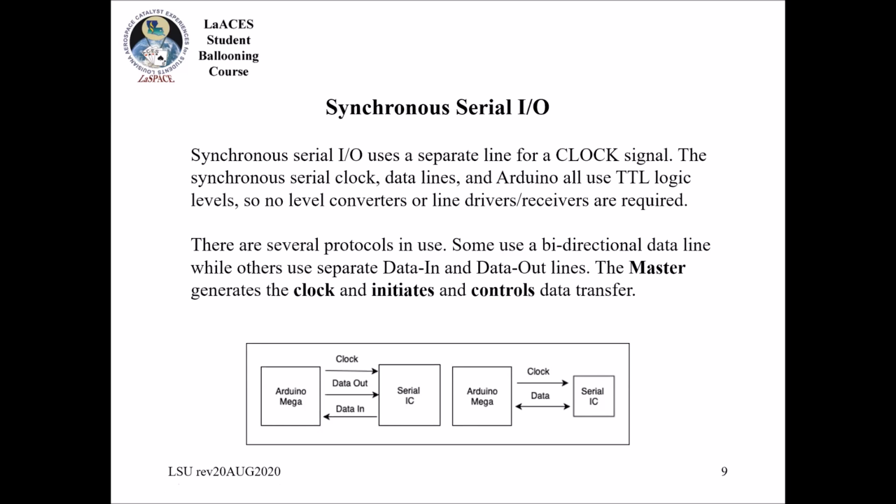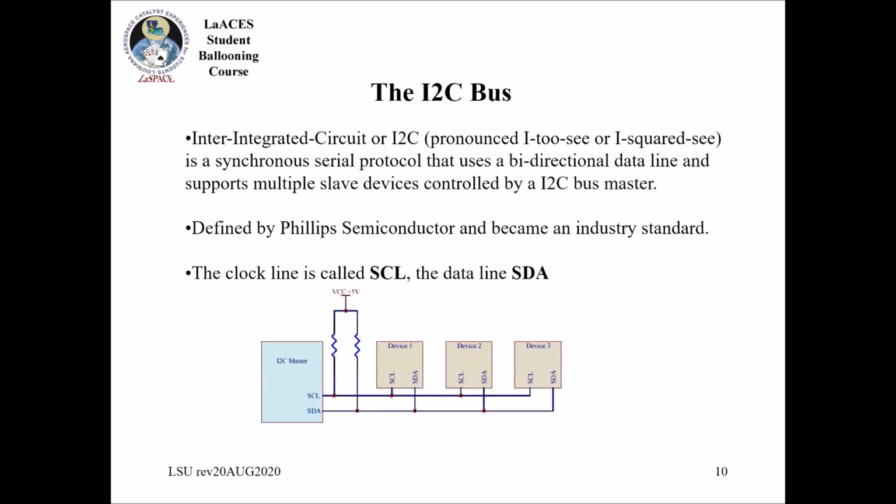So that's really important. Fortunately, with I2C, that's one nice thing, you just connect them all to the same pins, and you also don't require separate pins. These things also don't require a chip select, like what the SPI would use. With the SPI, you have to have a hardware line just to say, I'm going to talk to you. It's basically you're selecting that chip when there's multiple chips. So it's a digital signal. I'm going to select you.